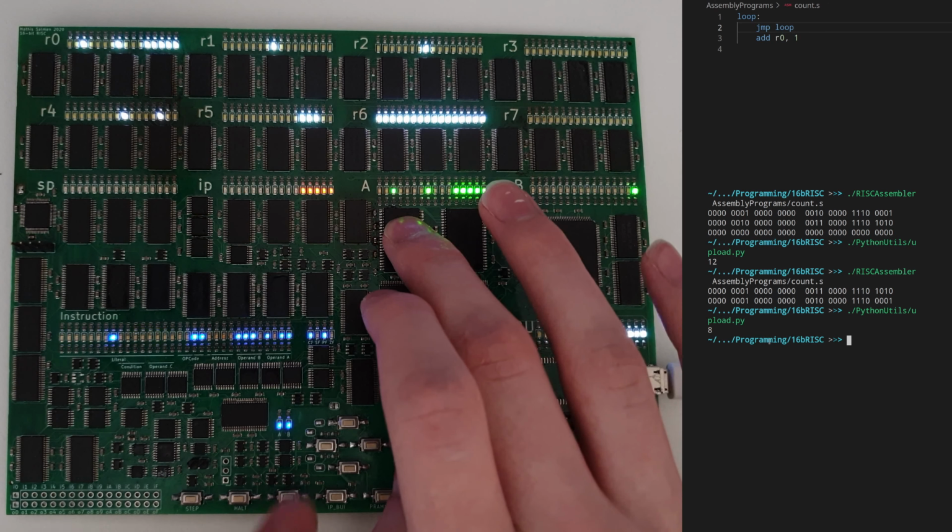I already uploaded the improved version of the counting program. If you actually go through the frames, then you will see that this counts 1/3 faster. And this is really useful for programs that spend a lot of time in small loops, something like a memset or a memcpy that spends a lot of time in a very simple loop if you do it for large areas of memory.